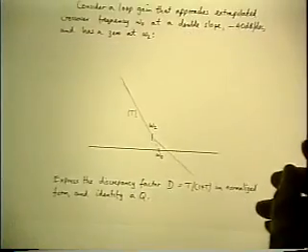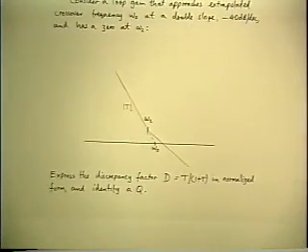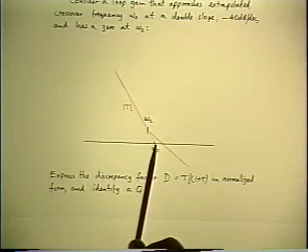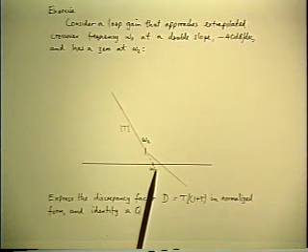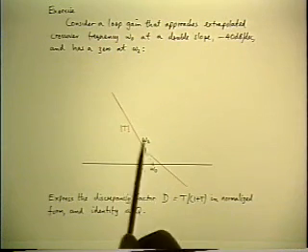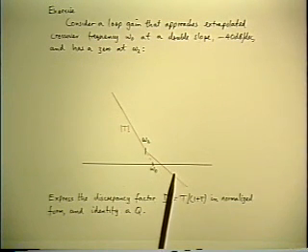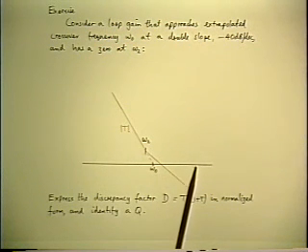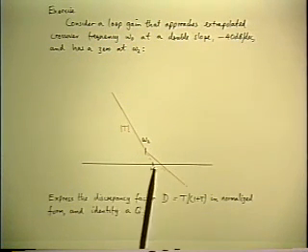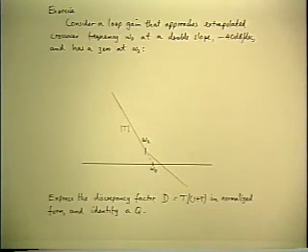This is the problem we've just solved, which has the same formula for the relationship between phase margin and Q factor. Now, that relationship is an internal property of this geometry, because it's to do with the relationship between the shape of the loop gain and the axis, which is what determines the D. So to show that it ought to be the same relationship as the previous problem, all I have to do is show that it's the same problem.